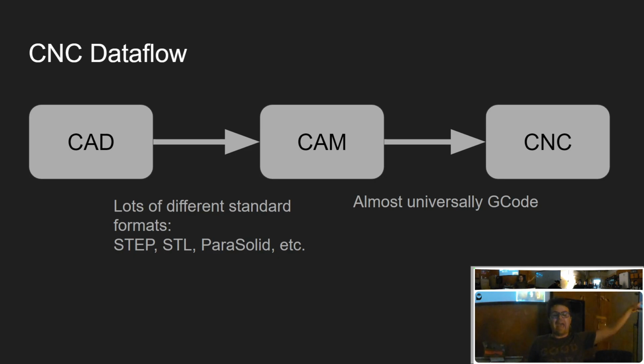The going from CAD software to CAM software portion has at least mostly been solved today. I would say the most common interchange format is the STEP file, which is good enough. STL files are used a lot, but they only approximate the geometry. But if you're having something sculpted, like for 3D printing, STLs are very common. And then there's a bunch of other formats. Almost all of the software can understand each other's different solid file formats to describe the shape of the part